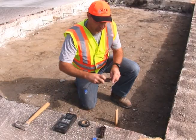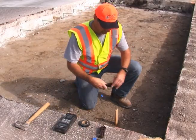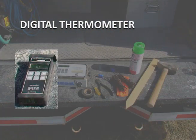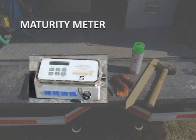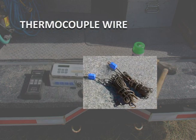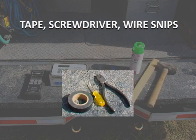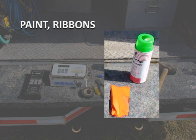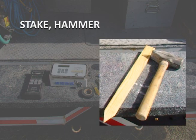The maturity method can be conducted using minimum equipment. Some of the required tools and equipment needed to perform the maturity monitoring are shown. A digital thermometer, maturity meter, Type T thermocouple wire with Type T mini connectors, and tools such as tape, a screwdriver, wire snips, paint, ribbons, a stake and hammer.